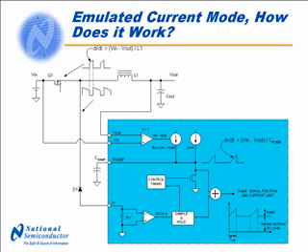Once the buck switch is turned on, the characteristic of the ramping current is dI/dt equals (Vin minus Vout) divided by L. This is the basic inductor equation. To emulate the ramping portion of the buck switch signal, first we create a current source proportional to the difference between the input and the output voltage. If this current source flows into a capacitor, the ramping voltage across the capacitor will equal dV/dt equals (Vin minus Vout) divided by Cramp.